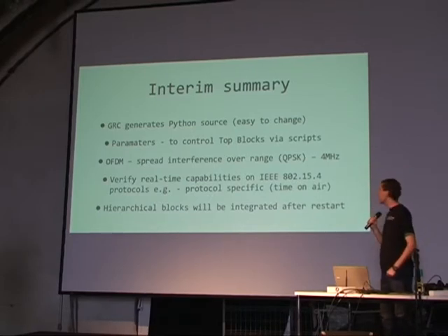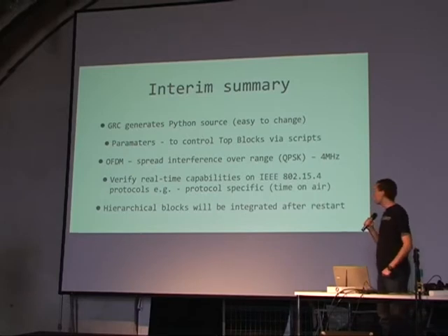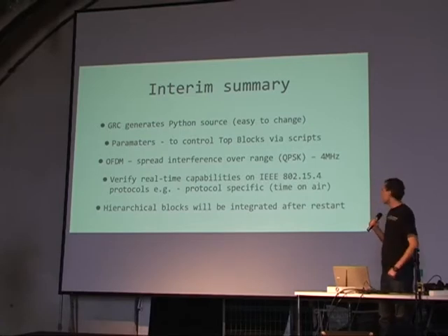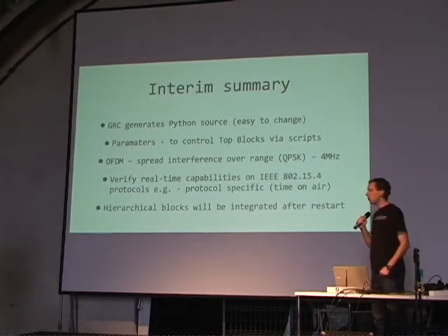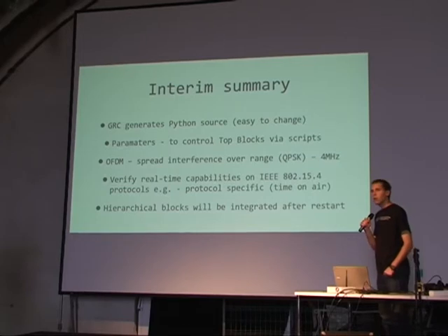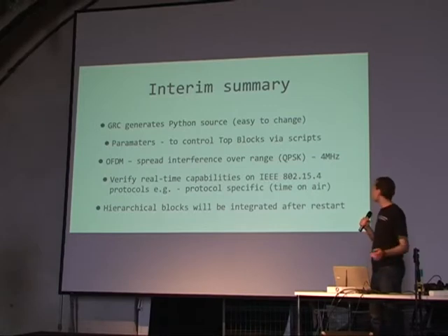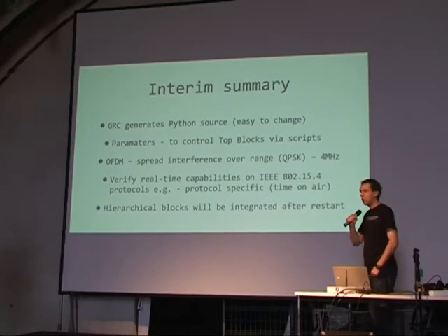And as I mentioned, this is useful to verify real-time capabilities on protocols like ZigBee, but it can also be used, of course, to simulate interference with Bluetooth stuff. And since there are real-world use cases for this, this is relatively interesting and relatively cheap to realize. If you compare what kind of laboratory environment you would use without software-defined radio and peripherals, and the approaches behind that. And you can use hierarchical blocks that integrate themselves into the GNU Radio Companion after a restart. So everything you do is available afterwards, and therefore you can have a library and reuse everything you do.